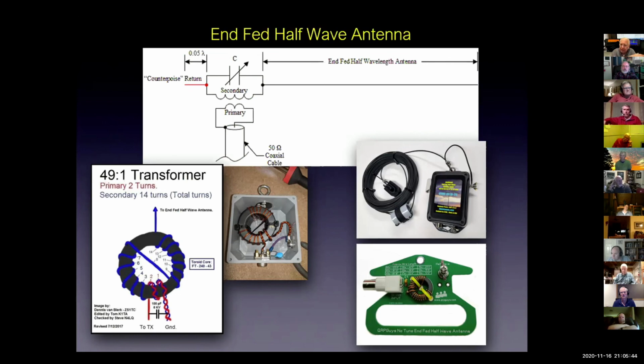And going back to the difference in efficiency, or whatever you want to call it, I did many tests out about 500 miles with my 40-meter group in the morning. I would switch as fast as I could between the two antennas to eliminate propagation and all that kind of stuff. And every time I did it, the end-fed was 1 S unit less than the resonant dipole. So what's that, 6 dB, Bob? 1 S unit? Yeah, supposedly.